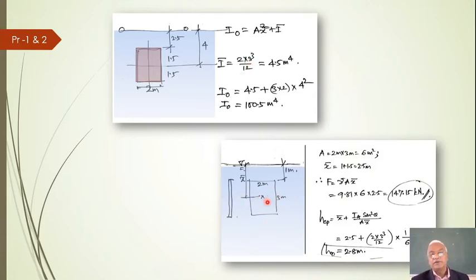Now look here, that is the edgewise view of a plane. But if it is seen from the front, what you will have is this, look, right? Now the upper edge is 1 meter below the free surface, this is 3 meter. So the area of the surface becomes 2 by 3, 6 meter squared. The centroid is over there at a distance of 1.5 meters. So X bar becomes 1 plus 1.5, that is 2.5.